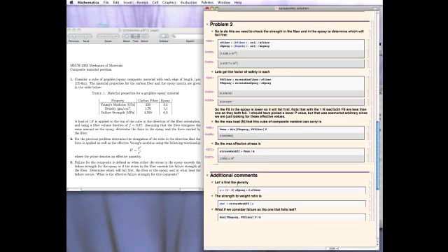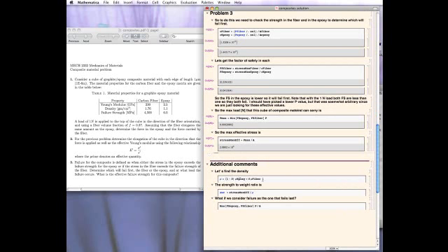Okay, down here I do some other ones. I get the density, and we also get the strength-to-weight ratio, and then I also look at what happens if we consider the other definition where failure is that the fiber fails. And you can see that obviously goes higher. That gives me 1.7 gigapascals. Okay.